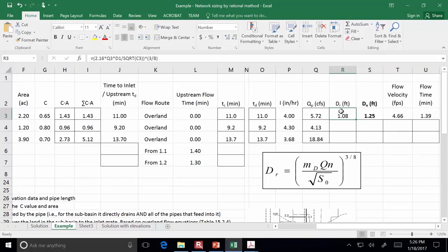But they don't make pipes that are exactly that diameter. They make pipes in increments. You know, there would be a 1 foot diameter sizing, then maybe the next size up from that would be 1.25 feet in diameter. And so here for the nominal size that I'm putting of 1.25, you'd have to just sort of have an idea of what pipe sizes are available. I'm going to assume that, in this case, the next step up besides 1.08 would be 1.25.